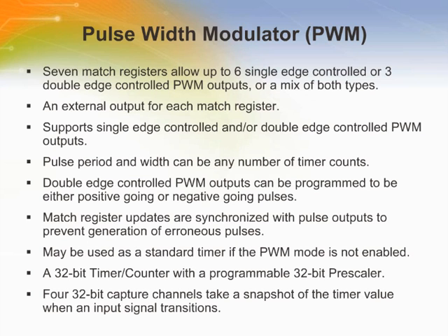It also includes 4 capture inputs to save the timer value when an input signal transitions and optionally generate an interrupt when those events occur. The PWM function is in addition to these features and is based on match register events.